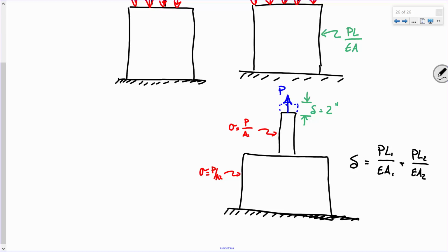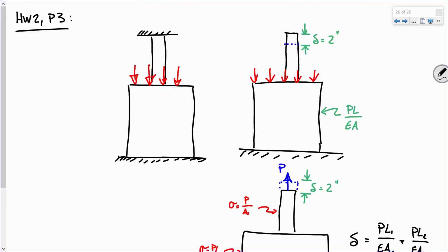So the idea is this. On this lower situation, if I apply a load here, I've got a force in this pipe and a force in this pipe. On the upper situation, I don't have any force up here. Does that make sense? It's just all about maintaining your equilibrium. It's the same tricks we've been using this whole time. You know, cut a section, determine the forces in each component. Make sense? All right. Anybody else have any questions?